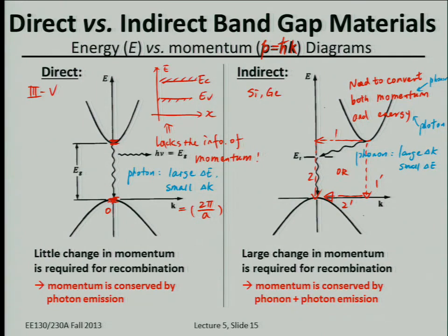So electrons and holes, when they meet up, can recombine. You have to conserve energy in the recombination process, but you also have to conserve momentum. It turns out in silicon and in germanium, electrons tend to have lowest energy when they're moving in the 100 direction, and this k vector minimum is located in the 100 equivalent direction. For holes, it's actually in a different direction, like 110. So basically, you need a lattice vibration to knock the electron to have the same momentum vector as a hole in order for them to recombine directly.